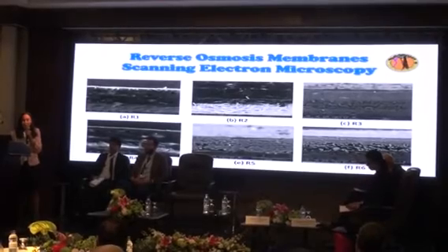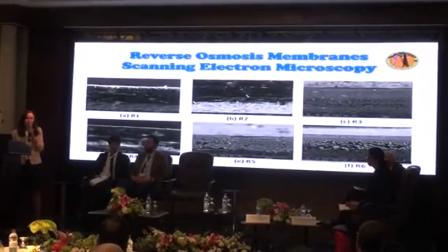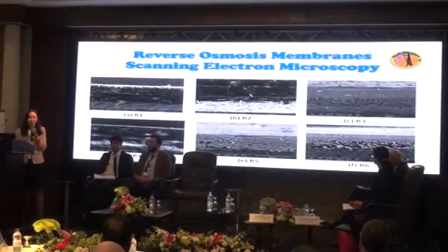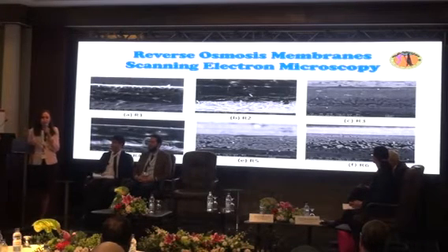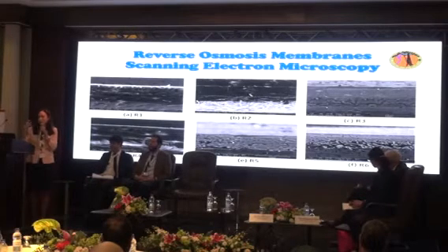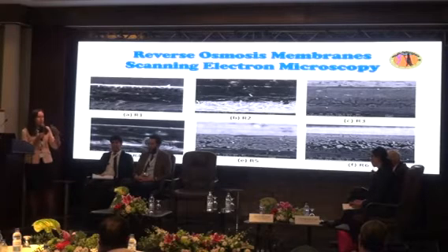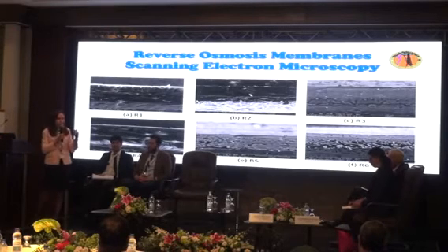The first one, of course, is without the new substance, and the first 2 are without the cross-linking or the coating, because as we will see, for reverse osmosis membranes, we always need the coating layer, this white layer, to make the cross-linking and to take us out of the range of nanofiltration to go to reverse osmosis filtration. So that's why we always need cross-linking.